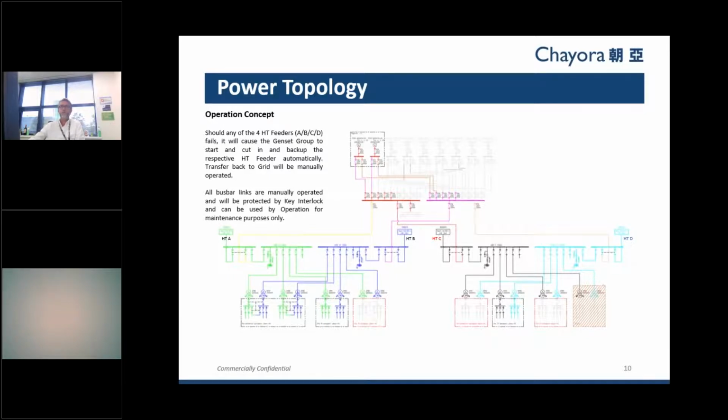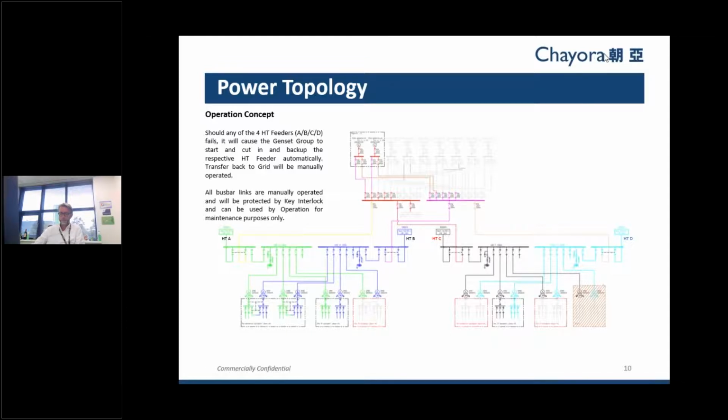Then our general topology for our UPS system is based on 2 types. The first primary type is the DR type, distributed redundant N+1. We also have a separate 2N system, UPS system E and F, for customers that want higher redundancy based on 2N. From here we have a distributed redundant DR system, ABCD, and a 2N system, UPS system E and F.